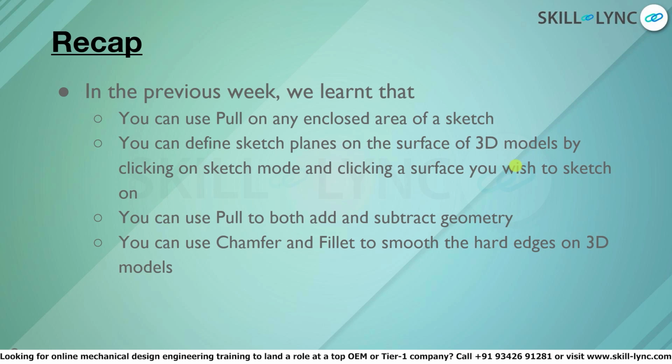We also covered that you can even create your own planes to later define as sketch planes. You can use the pull tool both to add and subtract or take away or cut out 3D geometry. We also covered the chamfer and fillet tools, which smooth or soften hard edges of your 3D model.